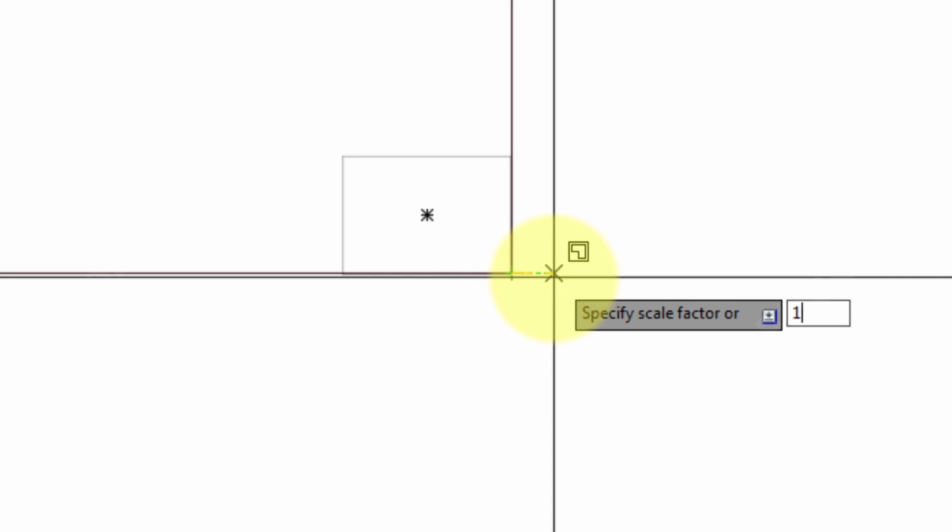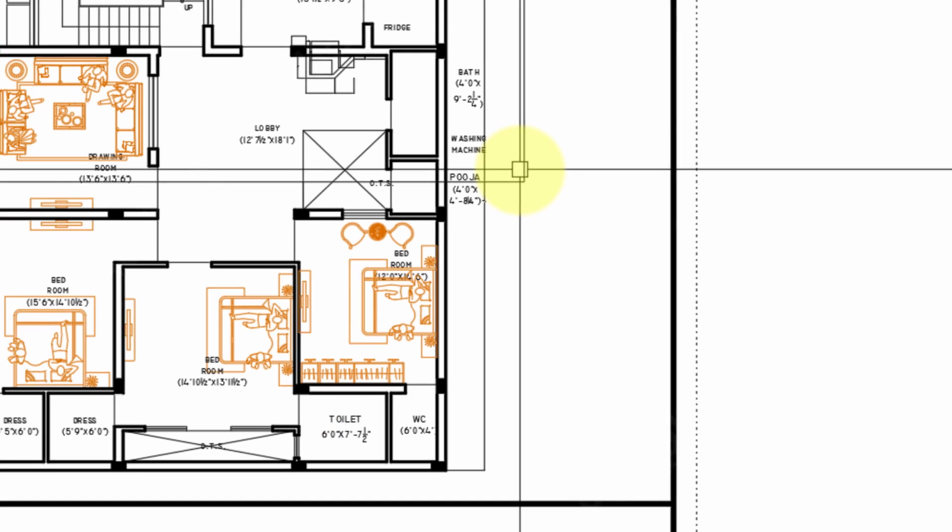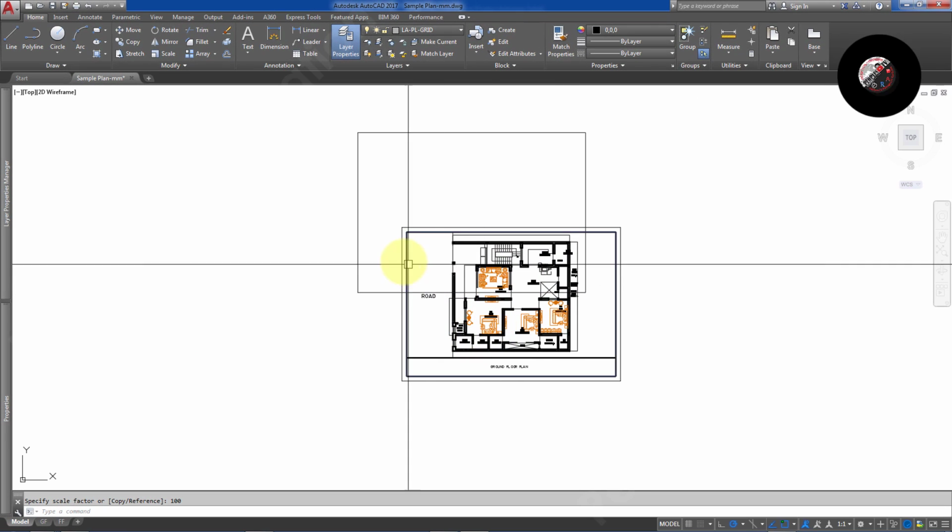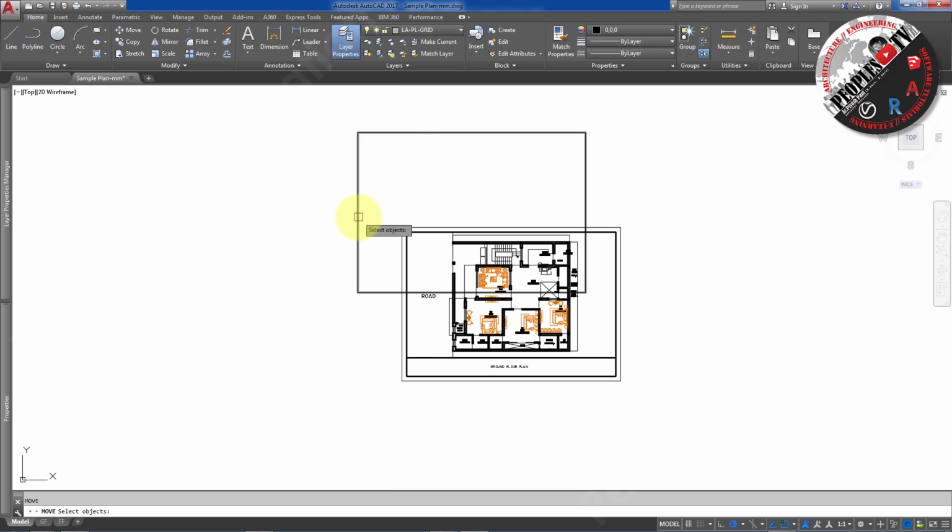Now let's take scale factor as 100 so that the printed drawing comes in 1:100 scale in an A4 paper. We can't take 1:96 scale as it's not a readable scale in millimeters. So we need to round it off to 100, which will increase the rectangle size slightly. And our drawing scale will be 1:100, which means 1 mm on paper equals to 100 mm in real scale.